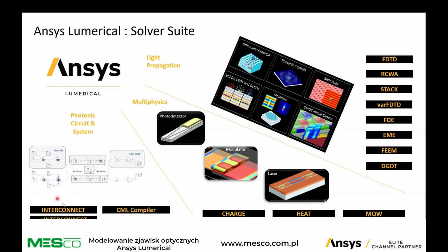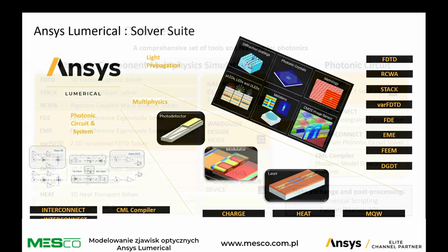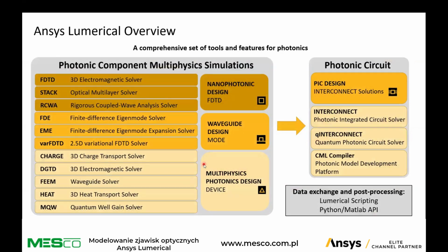So it allows you to calculate the quantum states and the probability of success and so on in a photonic circuit. So those are the different tools that we provide with Ansys Lumerical, and they are all packaged in different software or interfaces. So we have FDTD that includes the FDTD stack and the RCWA solver, and the MODE environment for waveguide design that includes the eigenmode solver, the eigenmode expansion solver, and the varFDTD solver.